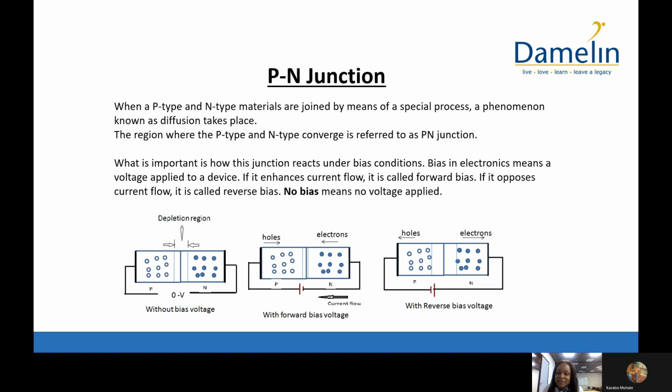So in that case, this reverse bias connection of the biasing circuit makes that semiconductor as if it is an open switch. So you must remember that. The way we connect our polarities to the semiconductors tells us whether we have a forward or a reverse. And when we have a forward, we have it as if it's a closed switch. And when we have reverse, we have it as if it's an open switch.